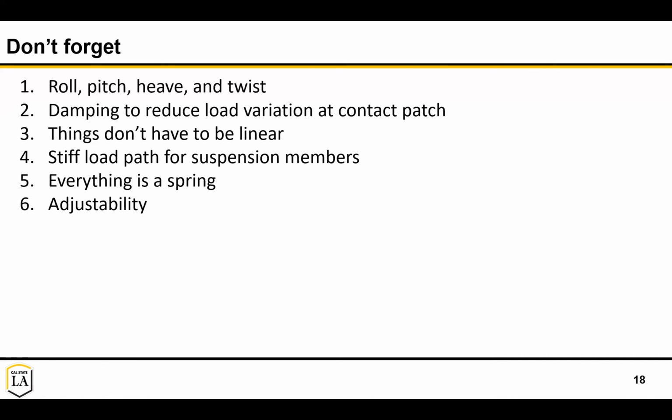So you also want to make sure that your system has some adjustability. You're not going to be able to build it exactly at the right camber angle and the right toe. So you probably want some adjustability for things like camber and toe. And that's also because, as we've said many times, you can't stress how important it is to test and to tune and to make modifications and to iterate, to really dial in all of these parameters that we've talked about on your suspension, and make sure they're meshing with your driver's abilities.